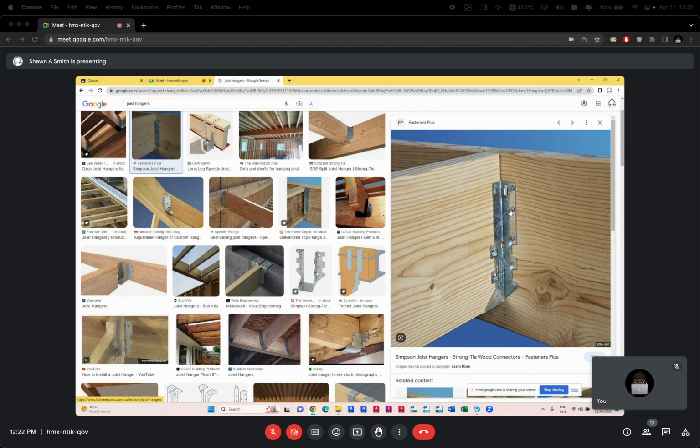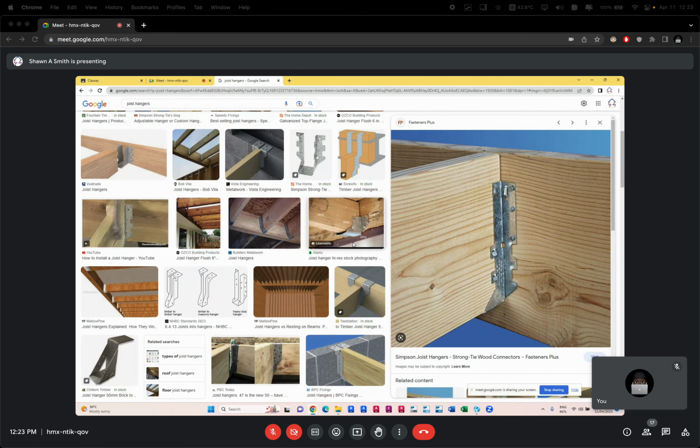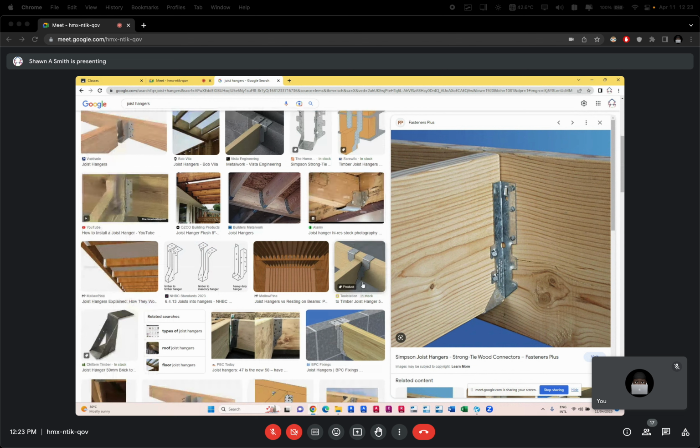The typical in Jamaica is for a man to just put a concrete base and put the timber in it. A lot of our timber columns are actually either placed on top of a slab inside the building, or placed in a mass concrete pad footing. And over the years, the base of it deteriorates because of moisture. And that's what happened. We don't really have all these fancy inserts and so nobody's gonna sell them. And you can't blame the hardwares, because if people are not using timber that much, why buy something from overseas only to have it there on your shelf for decades, not being sold?